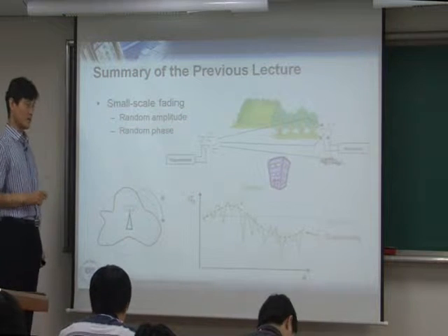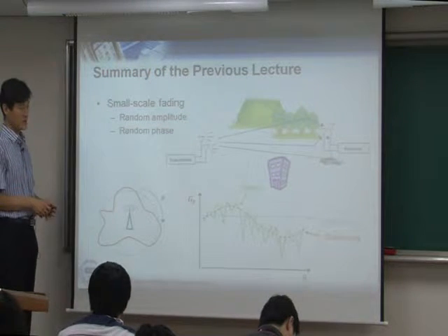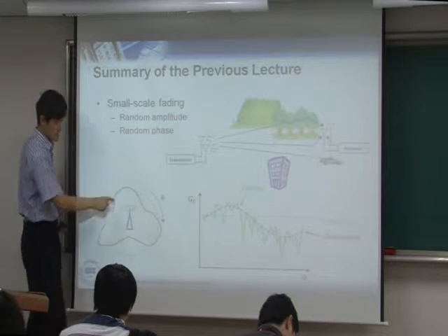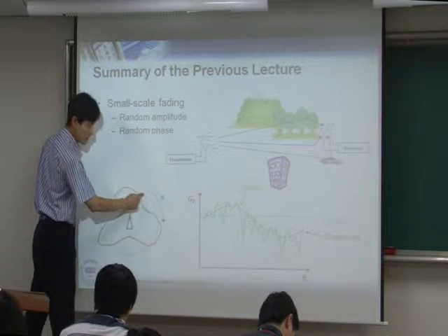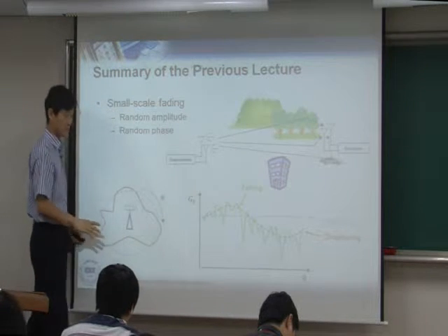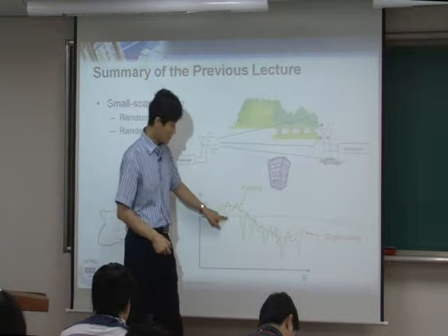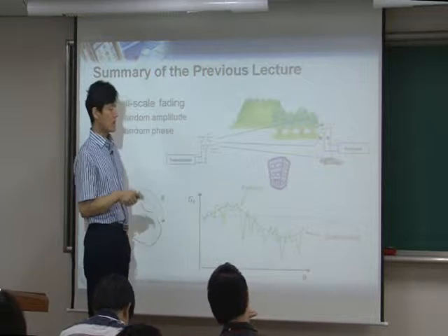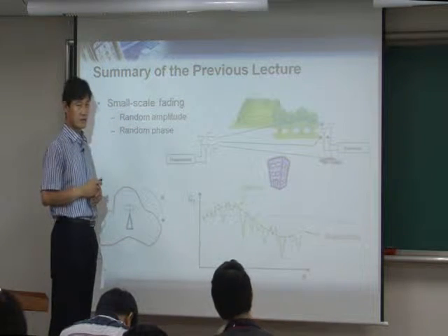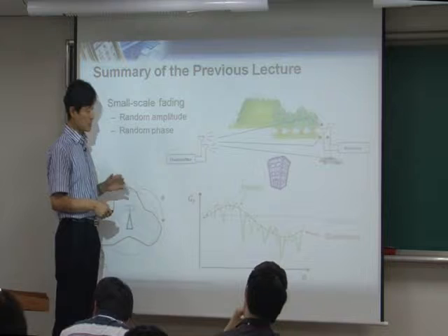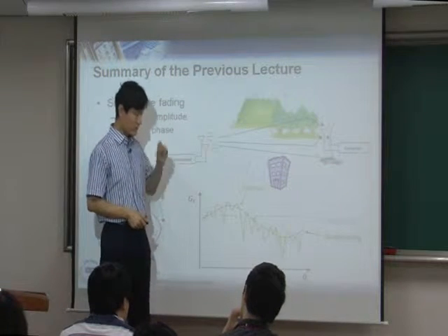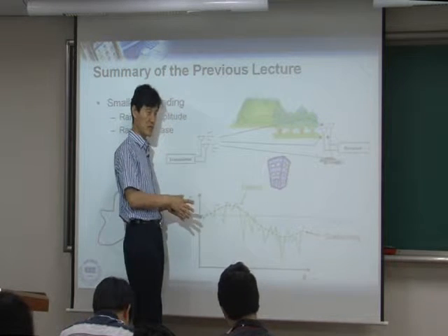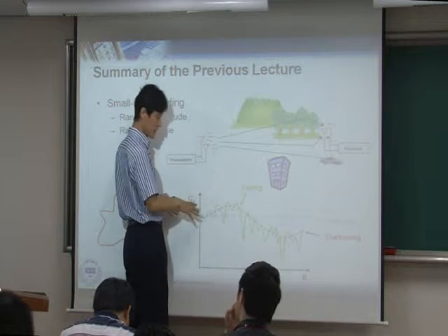If there's only path loss, then since I'm drawing a same-distance circle, all these users along the circle should receive the same thing. So received power should be flat in this diagram if there's only path loss. But as I said, that's not true. You have shadowing. Because of shadowing, your signal fluctuates based on a Gaussian variable. Again, this is just an instantaneous snapshot.